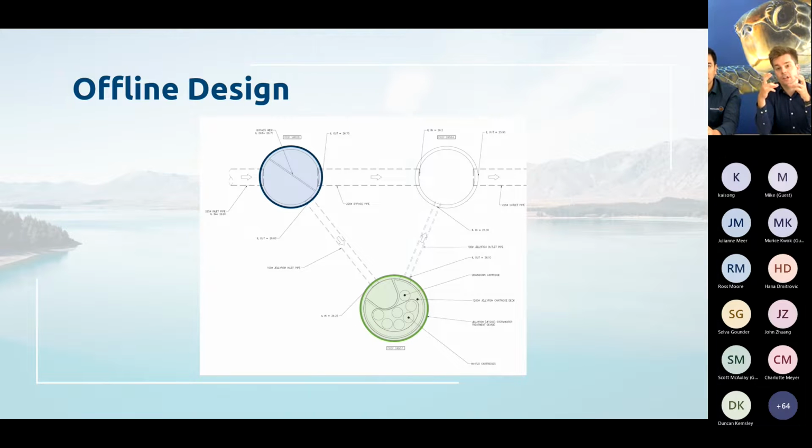We then have in this case the Jellyfish, which is configured off the main line. It is offline. And there is a weir that is placed in that upstream manhole that is set at the driving head level of the Jellyfish. So the level of the water within the Jellyfish that we need for the device to operate at its design treatment flow rate, water will preferentially flow to the Jellyfish. And then in the peak events, water can overtop the weir and scoot straight out and bypass the Jellyfish.